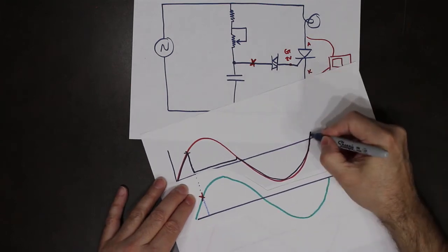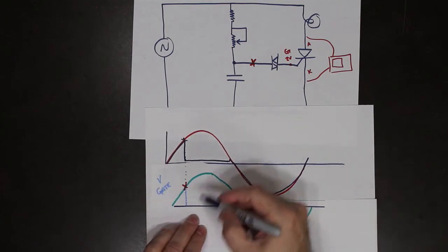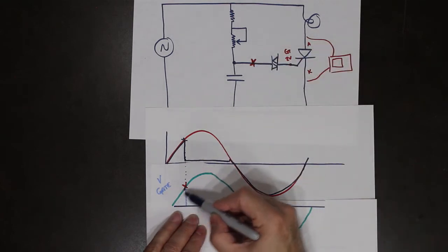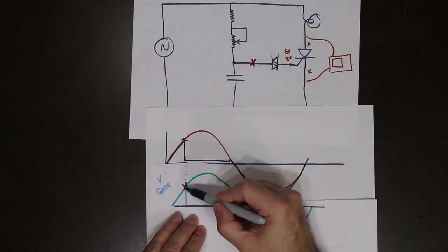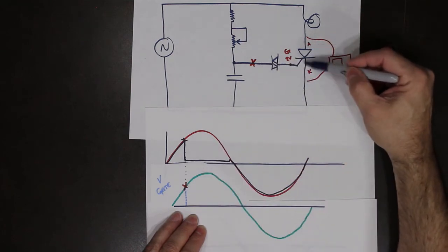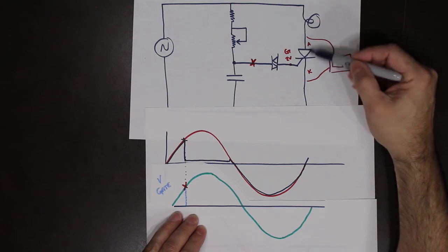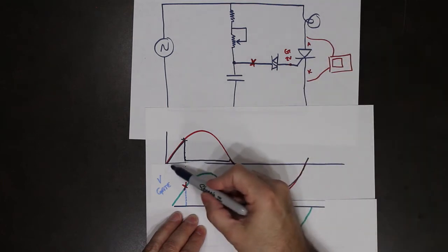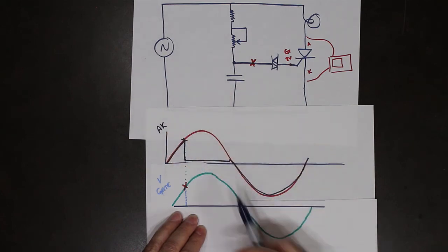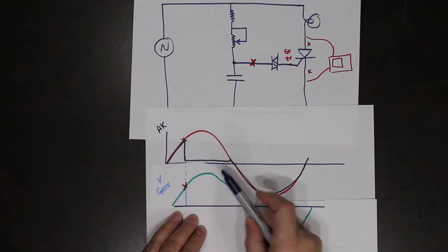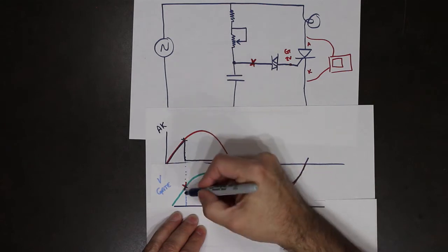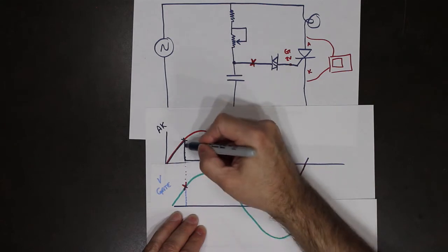And then the whole thing repeats itself. So this is the voltage we're looking at that gate. So this waveform here, point X, that's when there's enough voltage to trigger the SCR and get to conduct. So if we looked at the voltage anode to cathode, it would be this black value here, or this dark gray. So where it triggers is where it turns on.